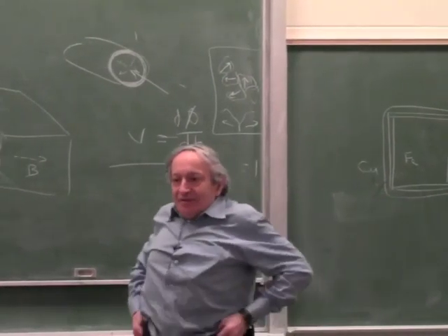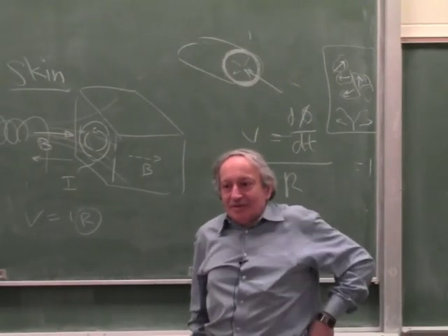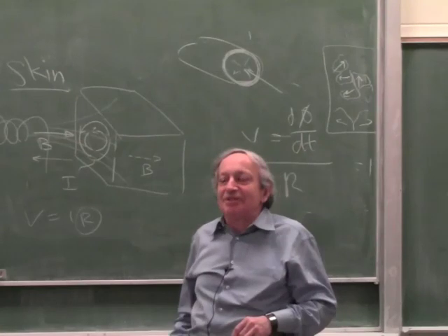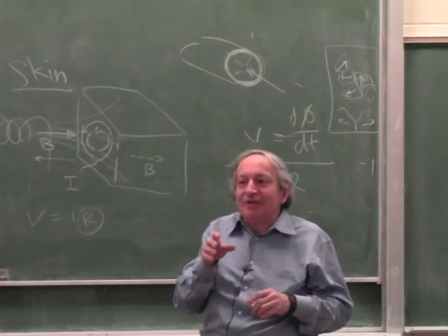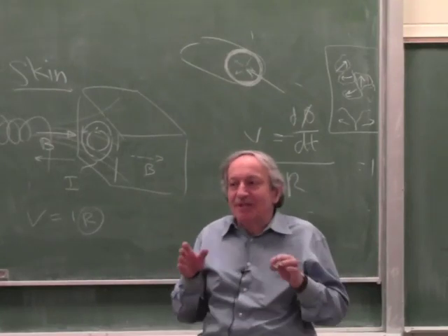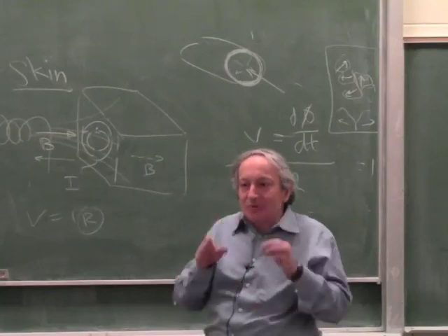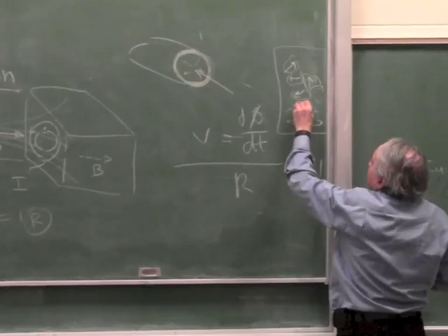You're saying that as you apply a magnetic field to iron, these pieces inside are mechanically moving around? Not mechanically, but the magnetization of them is moving around. Let me explain this again. The magnetic domains are not the same as crystals. There is some zone which is magnetized this way, it has a boundary, and another zone magnetized this way.